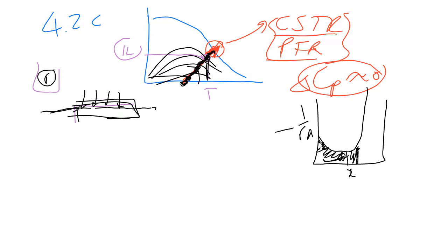Some people ask the question, is the energy balance the same? Yes, it is the same, but because I don't jump to a certain point when I operate, like in my CSTR reactor, where there's the sudden jump, I gradually climb up this hill. One of the advantages of this in a PFR is that I will never have the issue of multiplicity. It's not possible to exist here, right?